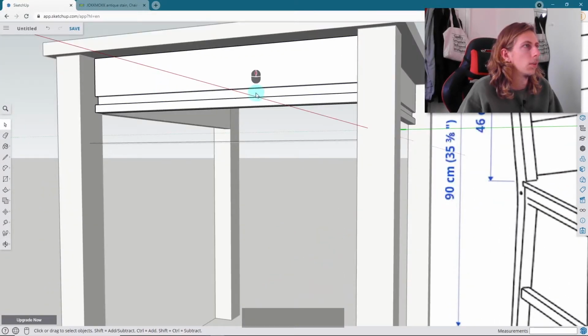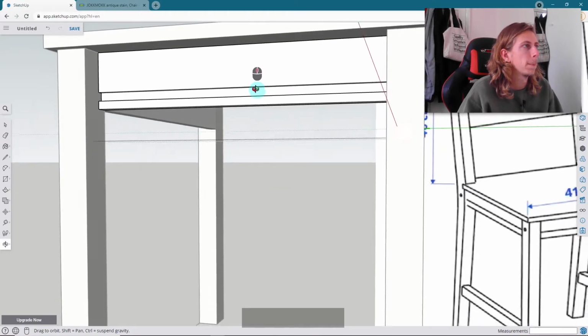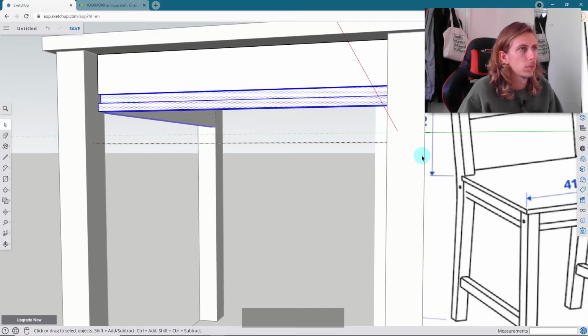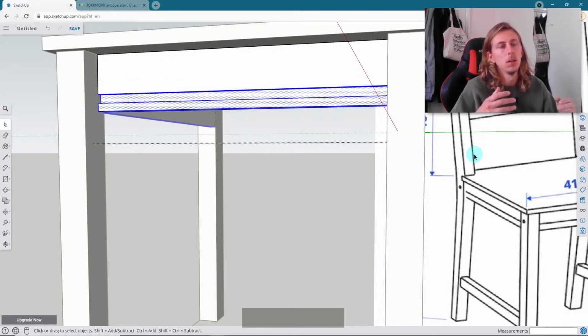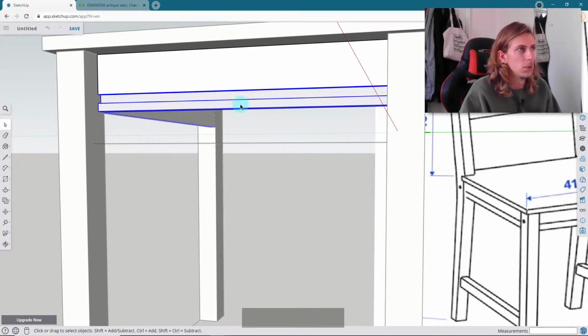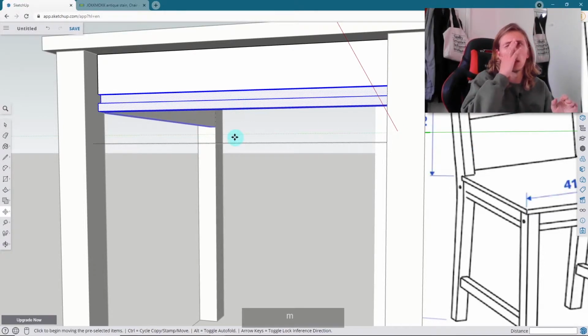So to adjust that, what you can do is you come into one of them, and if we drag from left to right, we select basically anything within the selection we make, and we can actually use the move tool to essentially stretch the parts of the object, if that makes sense. Kind of move them without having to actually manually push pull them or anything like that.